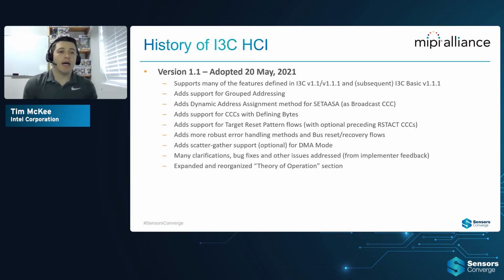And so we're excited that we're getting everything lined up for implementers to go out there and really put it to use. So what did we bring with this new HCI? Support for group addressing, dynamic address assignment with CCCs, CCCs with defining bytes, target reset patterns, all of these great features that will allow your host controller to really utilize I3C to its best ability.